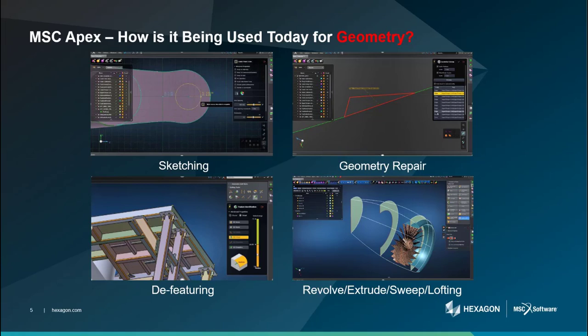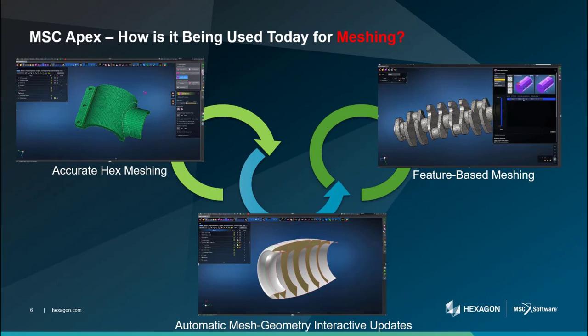How is Apex being used today for geometry? Well, things like sketching, geometry repair, defeaturing, and revolve, extrude, sweep, and lofting are things that you'll find in Apex are next generation and quite useful. In terms of meshing, MSC Apex is being used to maximize element quality for hex meshing, feature-based meshing, shell meshing, and also if you make any automatic mesh geometry interactive updates, the mesh goes along for the ride.